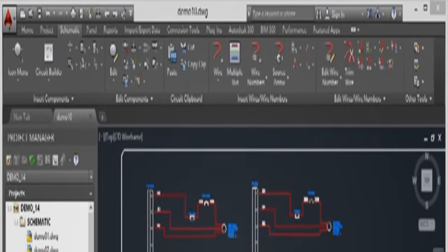Now I know that when I created the circuit to go into the icon menu, it was in inches. I know that this drawing is also in inches using the JIC Imperial Standards, so I can just set the circuit scale there to 1. I know it's going to be 1. I click on OK, and lo and behold, there's my circuit. So I'm just going to place it over here. I'm going to click there like so.